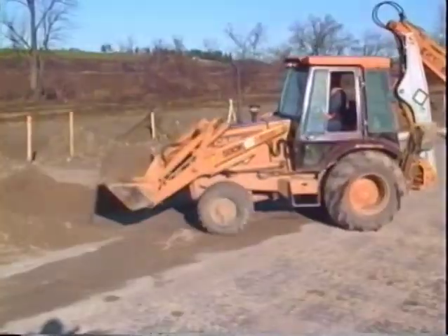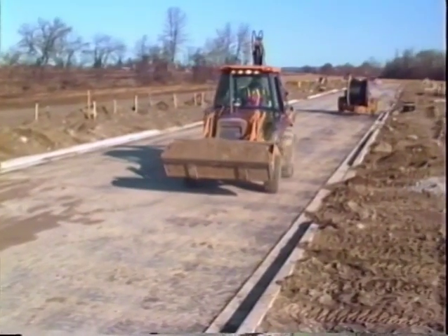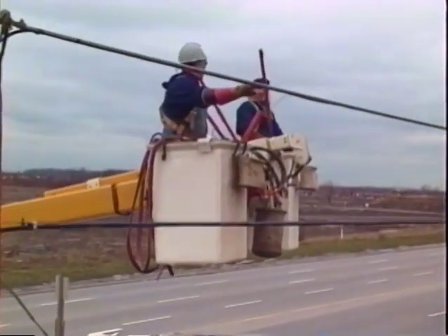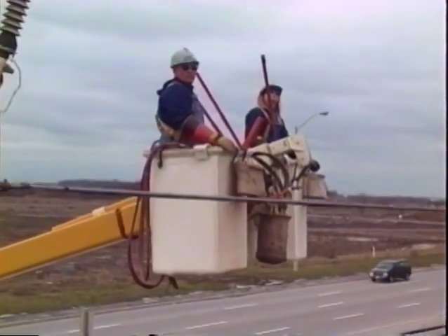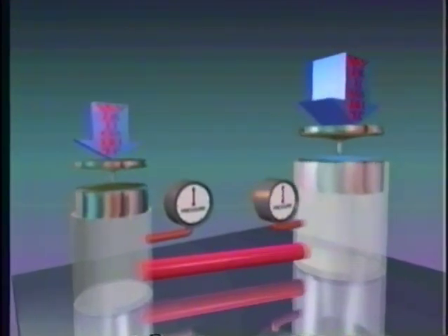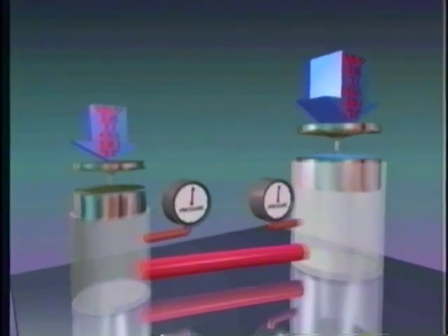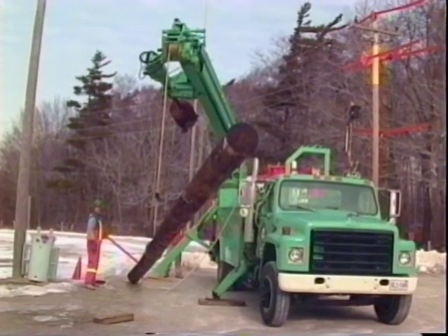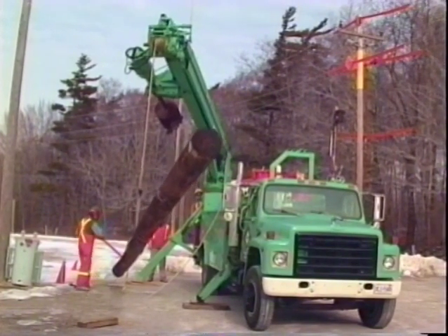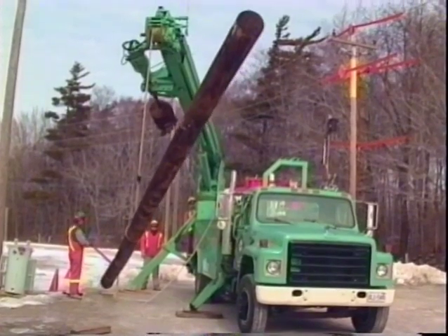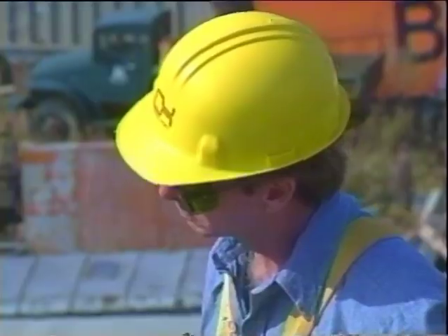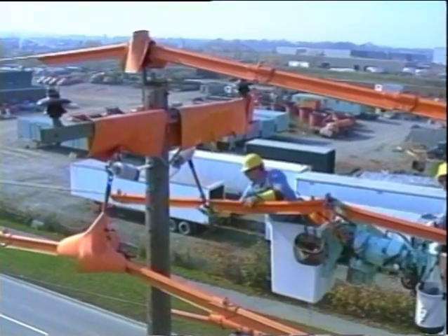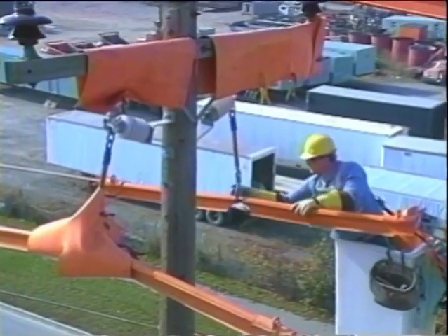Because of this ability to magnify force, hydraulic power transmission is used in many different kinds of machinery. But from a utilities standpoint, hydraulic systems have two special advantages: mobility and dielectric strength. Going back to the two-piston setup, keep in mind that the connection between the pistons does not have to be rigid. In utility work, for instance, most hydraulic hoses are made of neoprene. What this means is that a relatively small stationary power supply can deliver large amounts of power to moving components. And there is one other advantage of hydraulic power transmission that makes it especially attractive from a utility standpoint. If the materials used meet the appropriate standards, the hoses and hydraulic fluid are non-conductive.